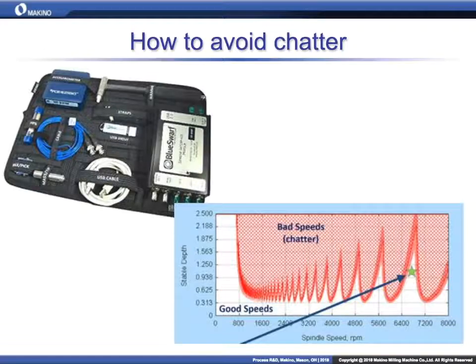And it's not something you can just know. You can't look at a half-inch tool and say, oh, yep, that one's at 712 RPM or 14,002 RPM or anything like that. You need measurement equipment to be able to understand how your tool behaves. Once you know how your tool behaves, you know how you can use that tool to its fullest potential. And the benefits are the biggest in aluminum, because in aluminum you're typically not limited by surface speed. You know, there's really no such thing as tool wear with carbide tools or PCD tools in aluminum.